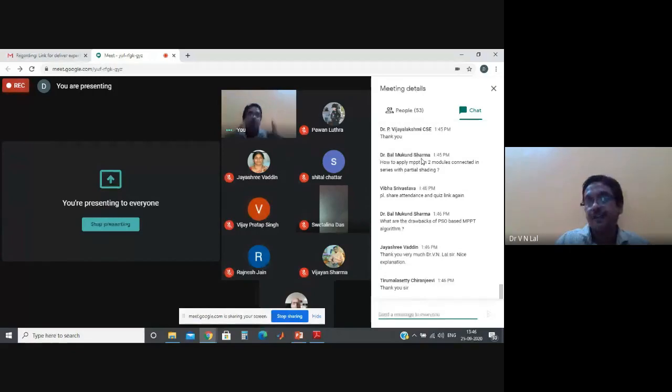In the programming interface, you give the instantaneous inputs V and I, and those two values can be used inside the programming box. You have written the program, so the present and previous instant values can be stored, the calculation is done, and the output of that box will be the voltage reference to the voltage controller, or the duty cycle reference to the DC to DC converter.